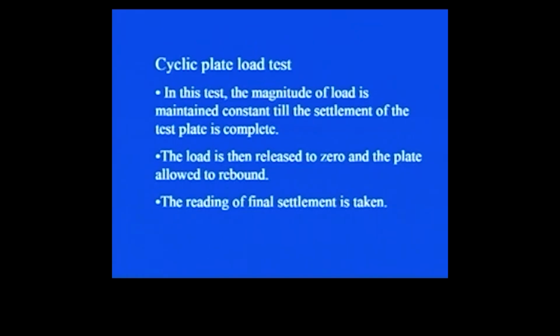In this test, the magnitude of load is maintained constant till the settlement of the test plate is completed. As the name suggests, it is cyclic, and since dynamic loads are coming into picture, obviously you have to go for cyclic kind of loading. This is an in situ test conducted in the field. A representative plate, a foundation, is there. Wherever you have to conduct the test, you put the arrangement at that particular depth, and then the loading arrangement is made in such a manner that loading as well as unloading can take place.